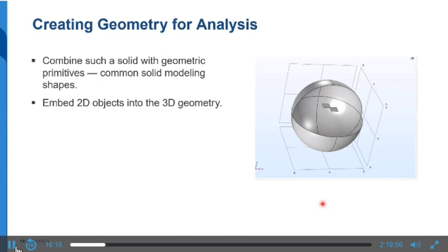And for example, as you can see over here, this is one sphere. In that sphere, we are having just one boundary. The example of this could be, if you are solving some electromagnetics analysis, you might be having some thin conducting surfaces. But in order to have any electromagnetic field, you will need to model air around that conducting surface itself.